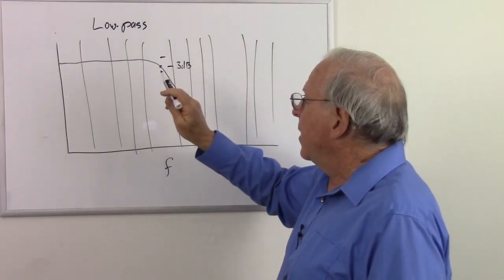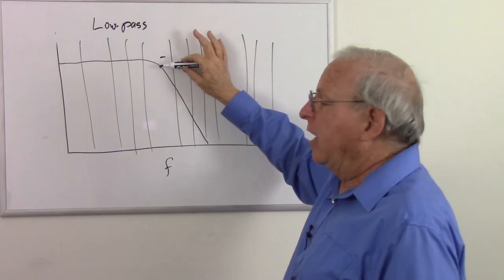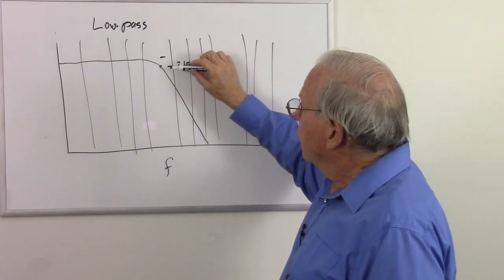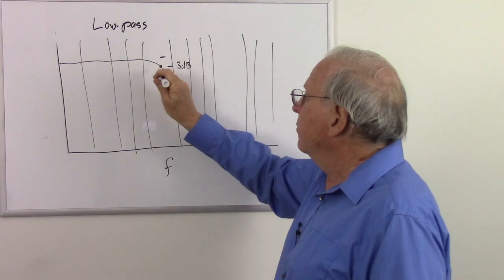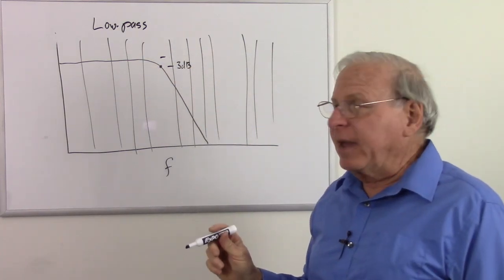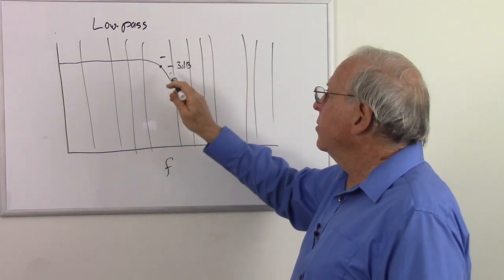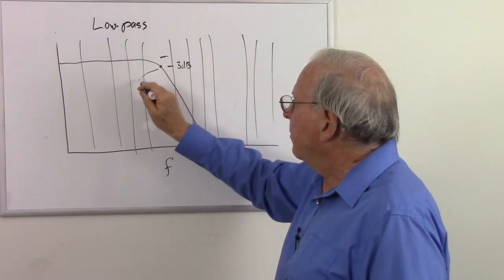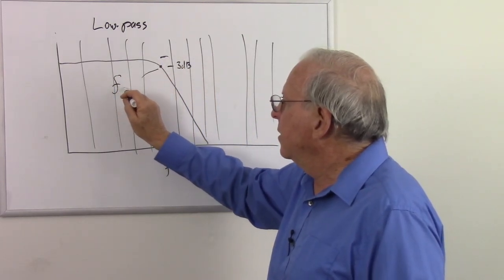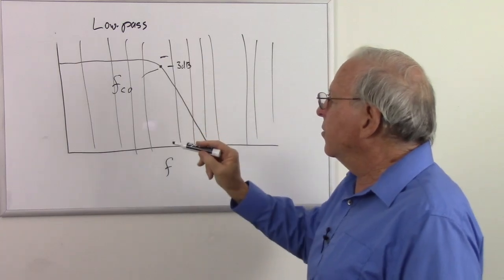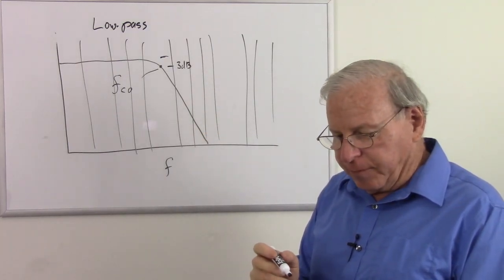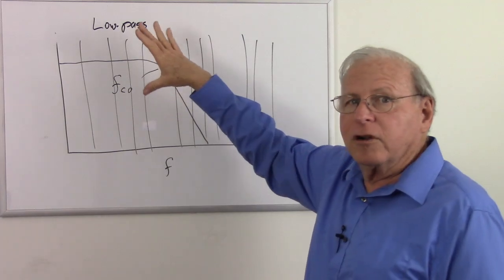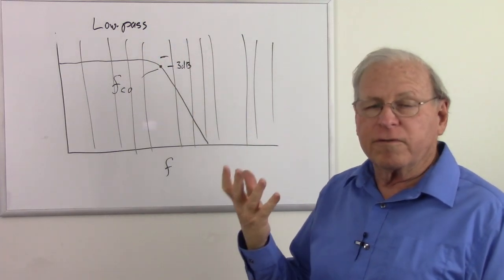So if we look at the power across the, in this case, low-pass filter, it's going to be the power across the capacitor. We're going to see that our cutoff frequency, our power being passed, is going to be 3 decibels below the peak. And so that is what happens at the cutoff frequency, it's the 3 dB point. So that's by definition where the cutoff frequency is, where the power transfer drops down by 3 decibels or 50%.